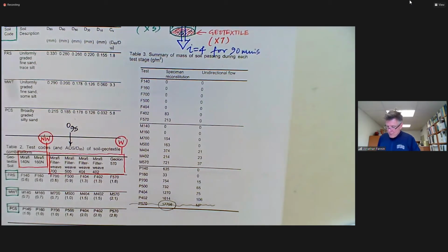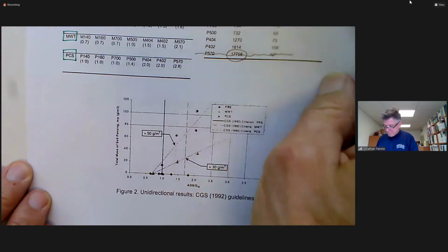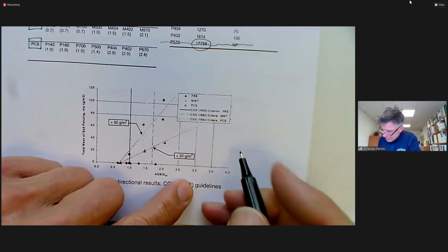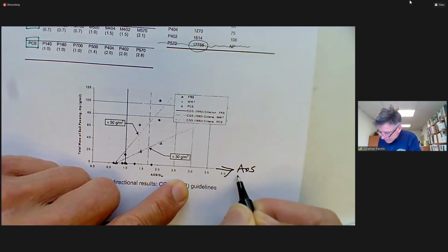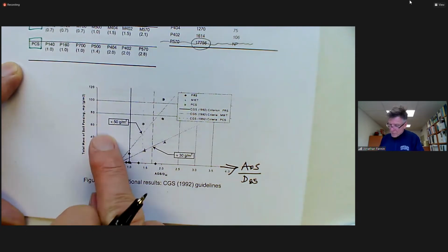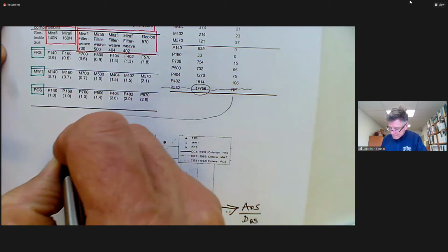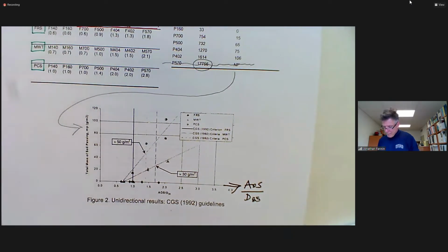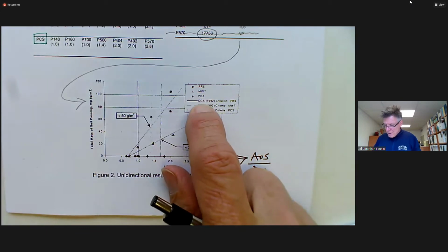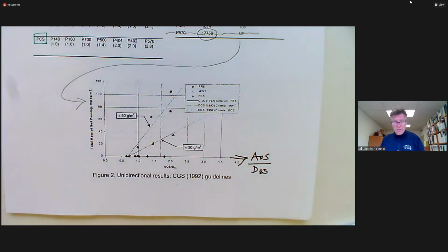And thus, the mass of soil lost, grams per meter squared, can be plotted against the opening size, non-dimensionalized by D85. If that's even a little bit grainy on yours, let's acknowledge that this is AOS over D85. That's the value in parenthesis here. And this is the mass of soil lost. That's coming from here. That would be this column over here. And an earlier version than the current version, but I don't think it's changed. So this is the Canadian Geotechnical Society, the Foundation Engineering Manual 1992. This was basically the Christopher and Holtz.